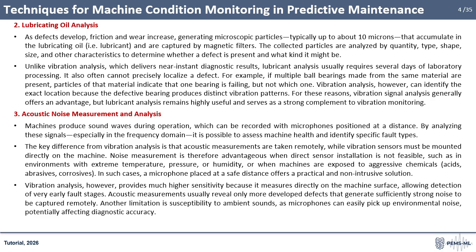Another important diagnostic method is acoustic noise analysis. Machine noise is recorded using microphones placed at a distance from the machine. Unlike vibration sensors, which must be mounted directly on the machine, microphones allow remote measurements. This is particularly useful when direct sensor installation is impractical, such as in environments with extreme temperatures, high pressure, humidity,